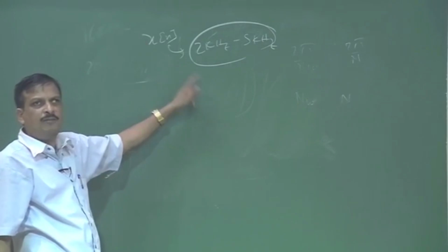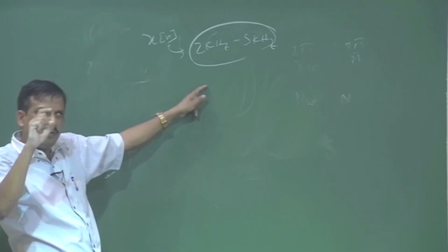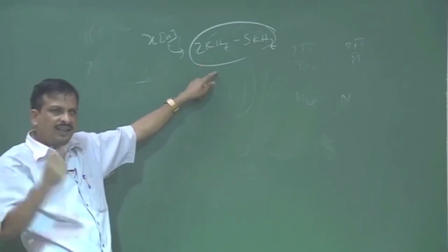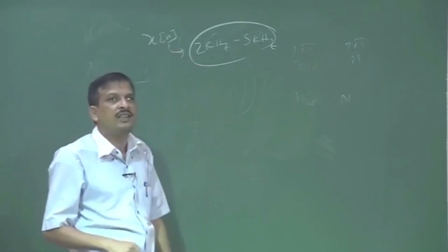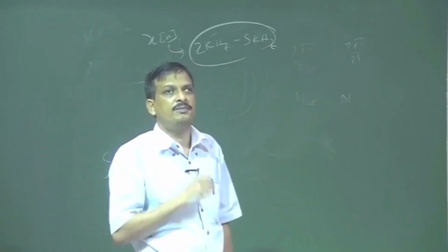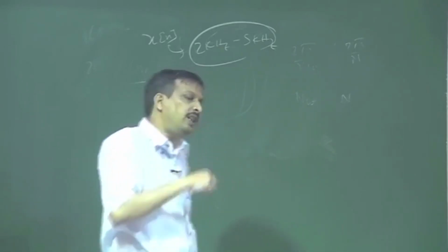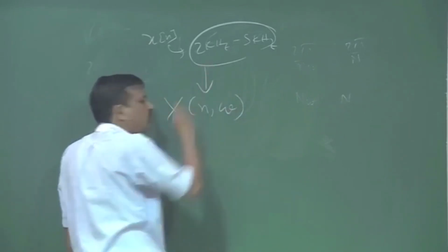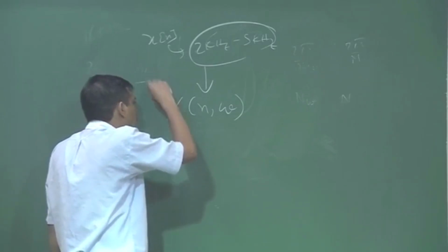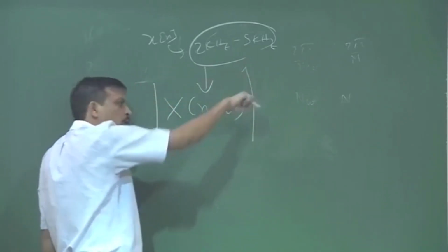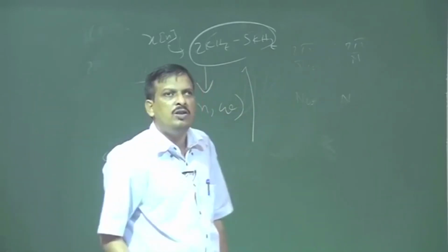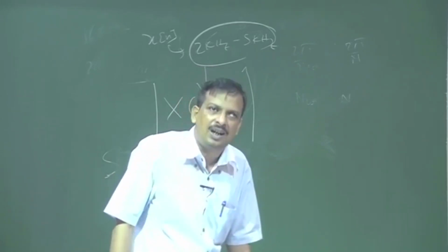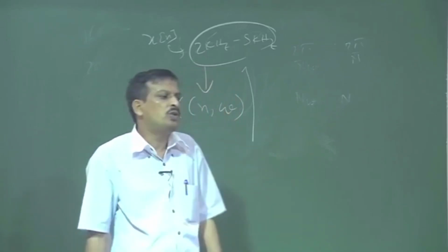So, I analyze x[n] in the frequency domain and reduce whatever I want, I modify the spectrum, and then take the synthesis again, I will get back x[n], which is the modified signal. So, I can do it in both ways. I can calculate X_n(omega) and do the modification in X_n(omega), or I can calculate X_n(omega), take the magnitude part and modify the magnitude part, then also recovery is possible. So, STFT or STFTM is used for signal estimation.